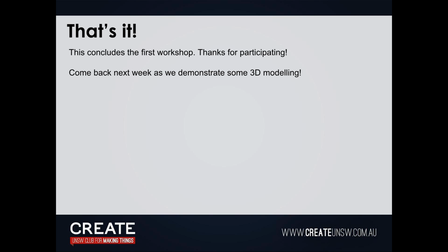Now this is very important. If you want someone to make something for you, you have something called dimensions, right? So obviously if I give this to a machinist, they don't know what is what, right? So it's very important that we specify our dimensions. So from there to there we know it's 15. You can drag that out. It shows you there to there 4.85, from there to there 20, and so on, right? And then we just do another one like this. That pretty much covers all your bases if someone were to make this.